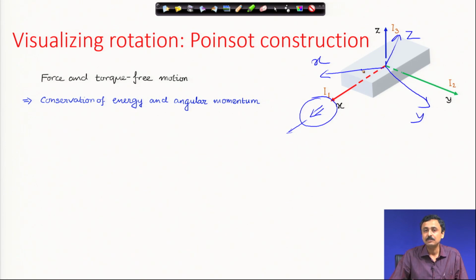Angular momentum vector will maintain its direction and magnitude in inertial space. The frame which is fixed to the body can precess, it can do whatever it likes, but the total angular momentum of this body is going to have the same magnitude, same direction. Therefore, its projection in these three body fixed frame axes will be changing. It will change periodically, if it is precessing, of course.